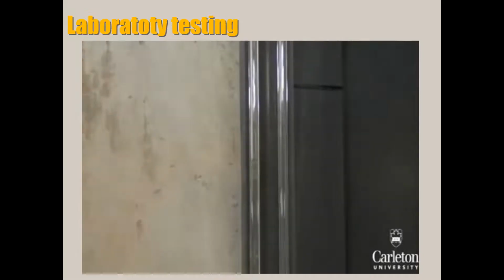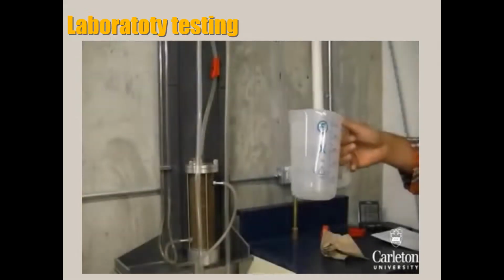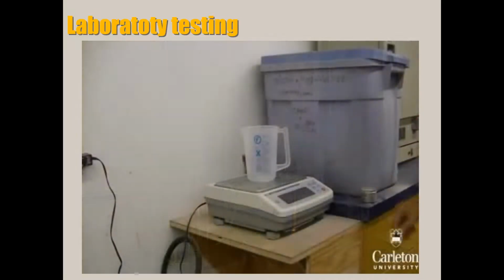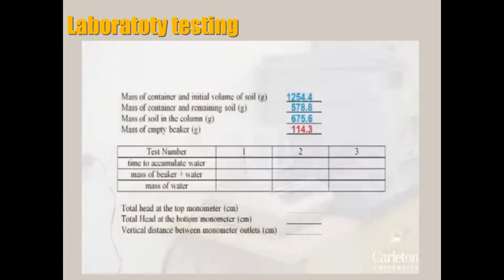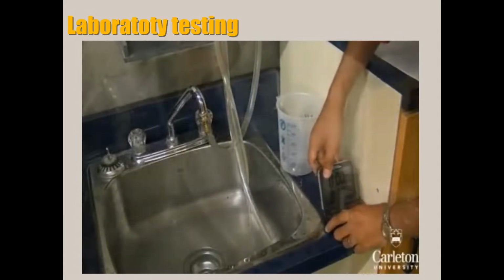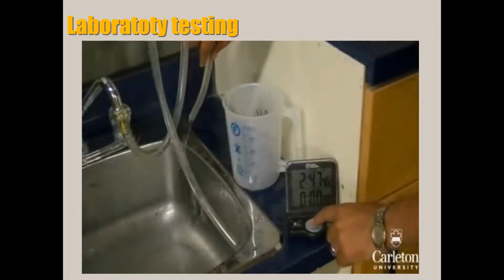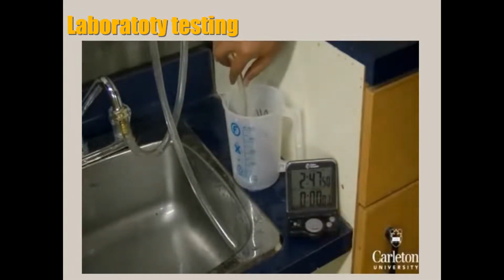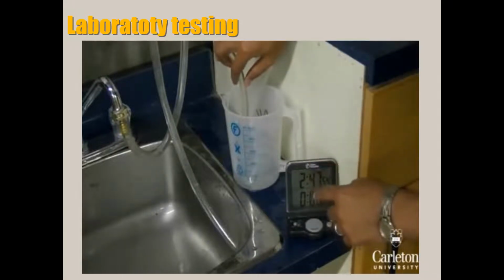Now we can start measuring water flow rate. Take a beaker like this one, then measure and record its mass in the table. We'll be using this stopwatch to record the time. Simultaneously start the stopwatch and begin filling the beaker with the discharge from the test cylinder. Here we are aiming to collect about 300 milliliters of water.